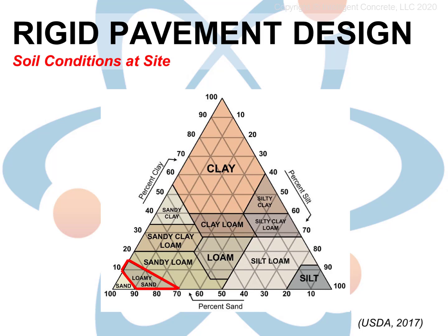This triangle breaks down the percentages of clay, silt, and sand contained in our soil, which is helpful since the designator SM only says that it's a silty sand, meaning it could be up to 49% silt and possibly even contain some amount of clay.